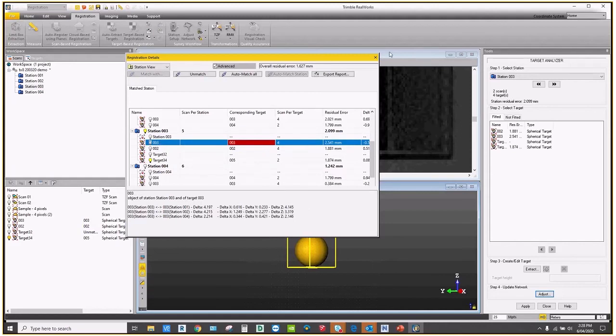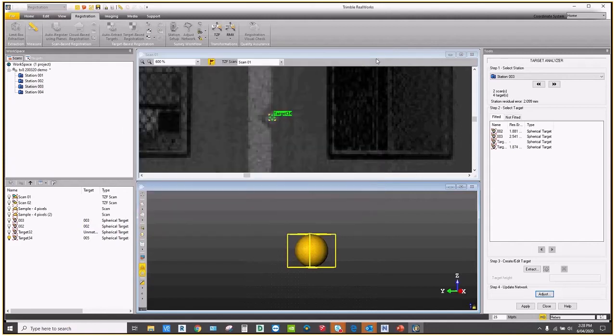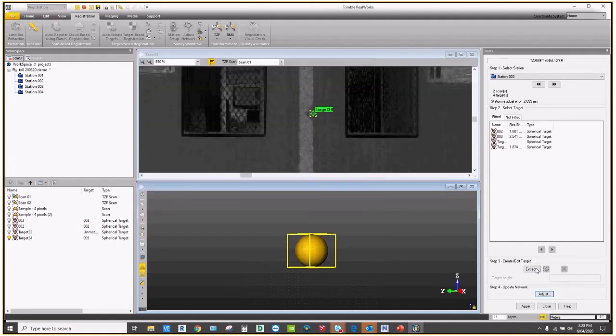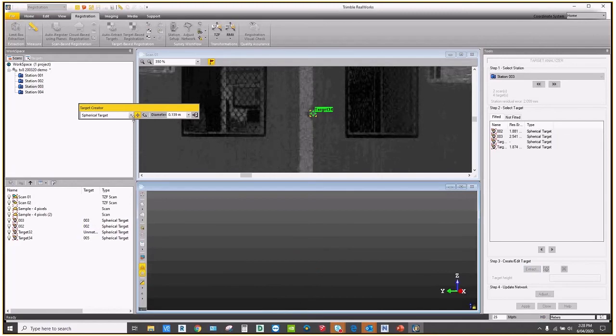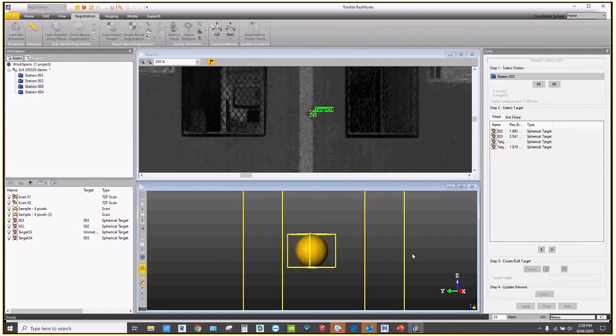You can also, as a really last resort kind of method, extract, as well as spheres and checkerboards, just points. So if you can clearly see a point on, you wouldn't do the corner of a window frame like that, but say a bit of signage or something like that, where it was good enough for you to get a registration result for your needs. Sometimes these bottom 2 suffice to do that. But if you've got spheres and checkerboards, it probably won't come to that, to be honest.